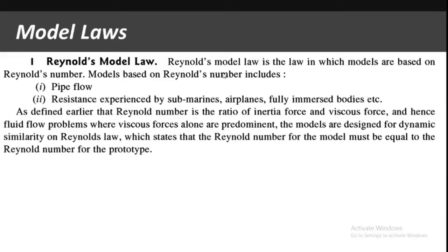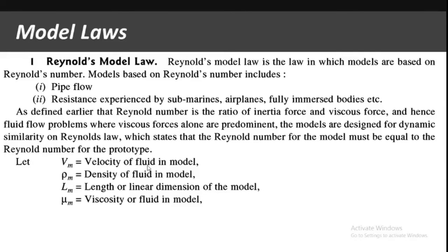Okay, so as defined earlier, the Reynolds number is a ratio of inertia force to viscous force. Hence, in fluid flow problems where viscosity is playing an important role, we check the Reynolds number. So Reynolds law states the Reynolds number of the model should be equal to the Reynolds number of the prototype. Okay, so Reynolds number of model and prototype should be the same.